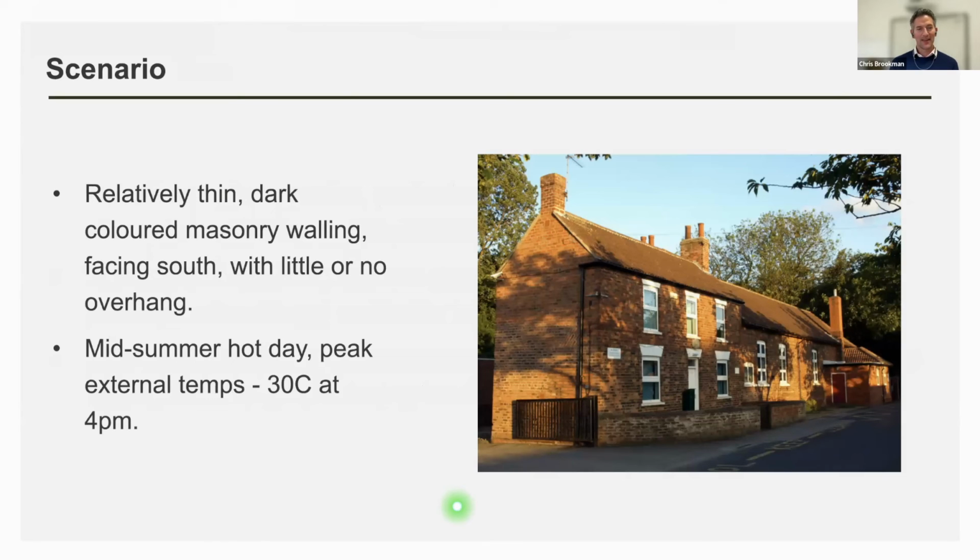So then really the final scenario is looking at more summertime temperatures. Looking at brick buildings, particularly, as Mark said, there is a huge variation in the density of brick and the thermal conductivity, particularly up around Manchester, Blackburn, those kind of areas. There's a lot of really hard, dense brick used to build buildings, and they have a conductivity of about 0.8, 0.9. Whereas the old historic bricks, London stock bricks, for example, go right down to about 0.4.